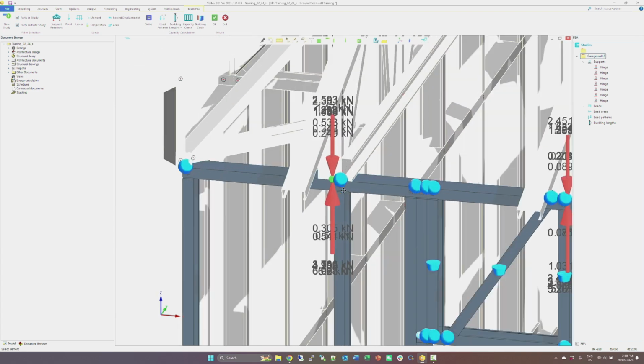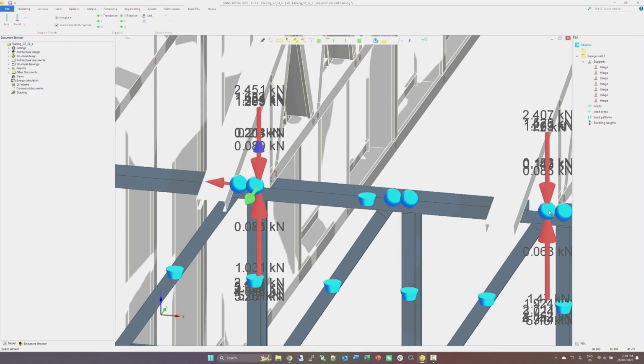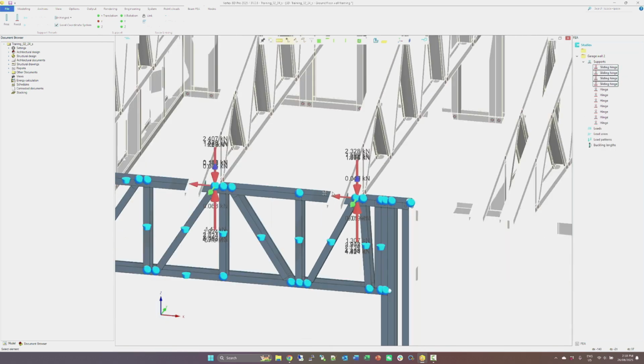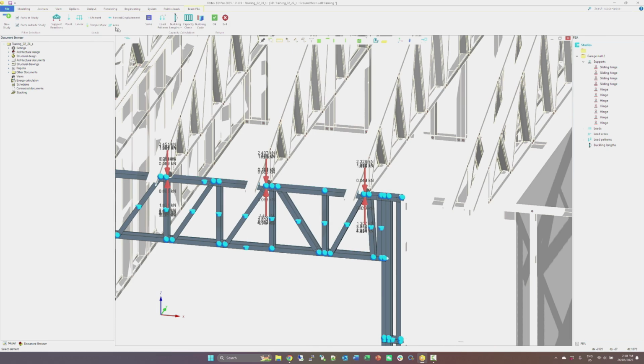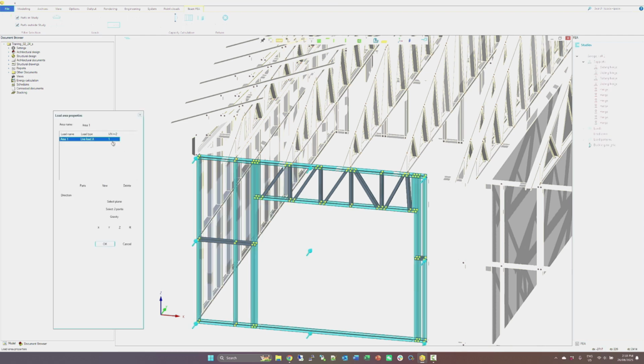After the load transfer has been done, now we just have to select those three nodes again and establish the lateral support from the trusses. Okay. Now we'll just add area loads into the FEA study as well. Make sure that we input the exact same wind load as our first FEA study.